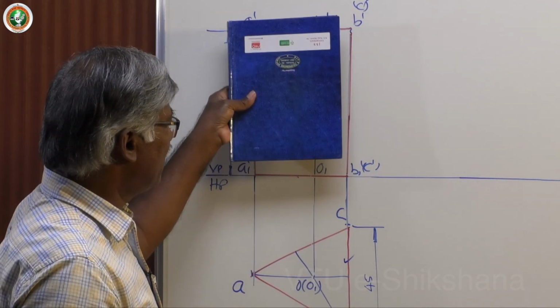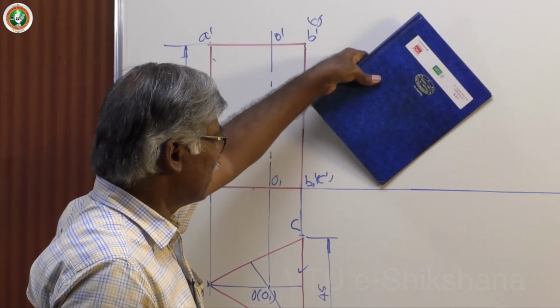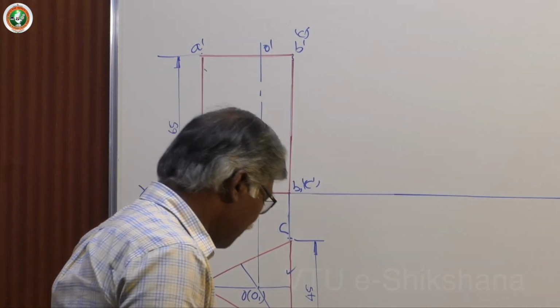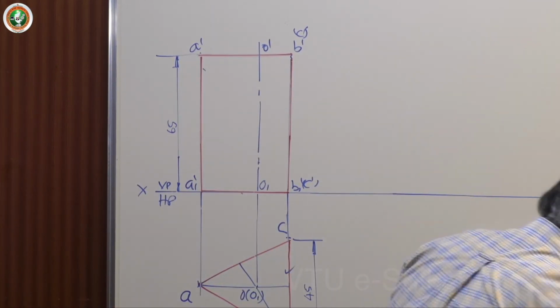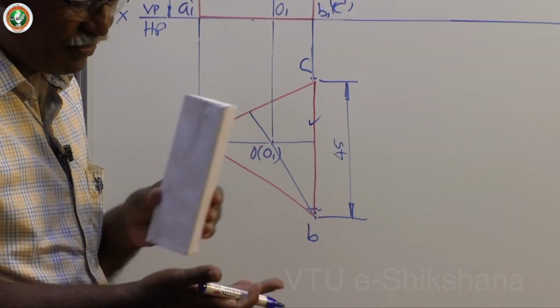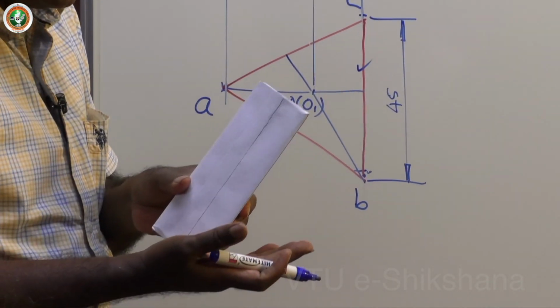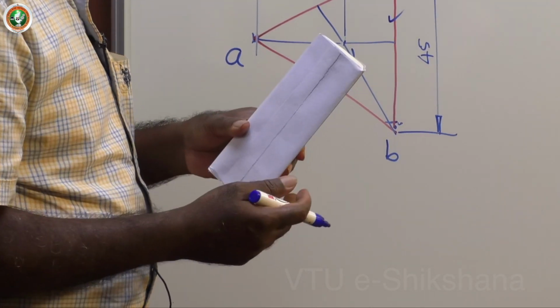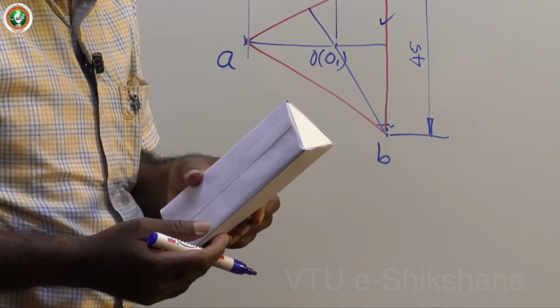Next, this is the front view. You must do it like this. So, first figure front view, second figure front view. Now, you can observe here, it's very interesting. This is the lateral face containing the base edge to be placed on HP. Fine. If the axis is inclined at 45 degrees, what happens to this? 30 degrees, what happens to this? This also assumes the same angle.